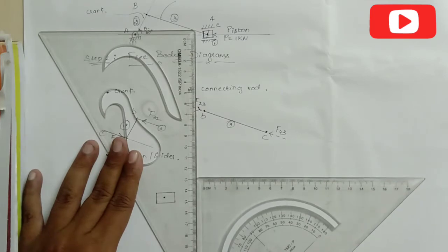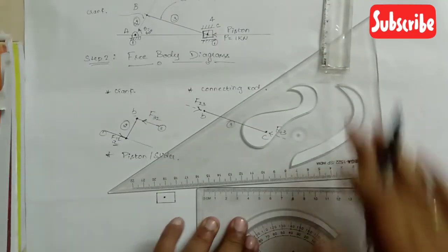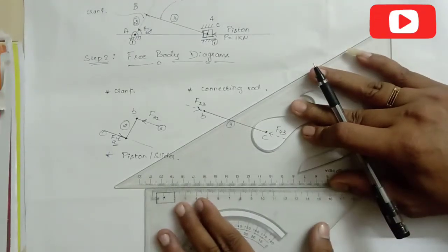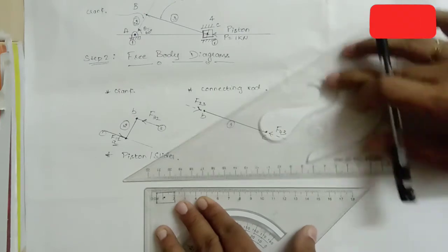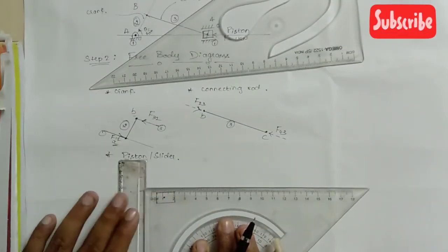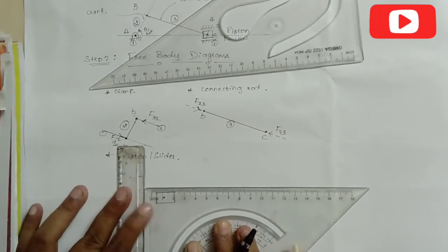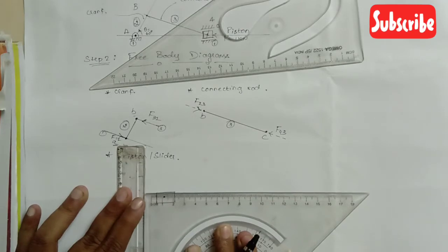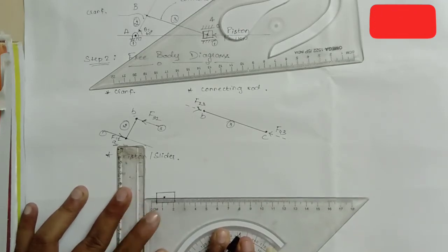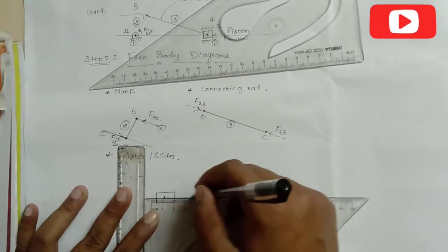Okay. And if you want to move this towards the left side, again butt this towards the upper face, and move your scale towards the left side. Again what you want to do, you want to move this in the downward direction. You can make use of all the scales you have. You can butt in this face, butt near this face, and push your scale in the downward direction. When you feel this is the center point, just draw the parallel line.